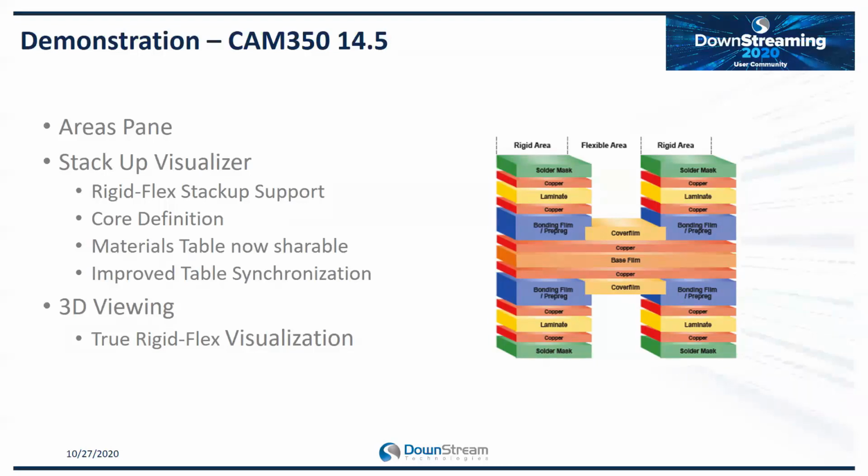2581 out of Cadence is pretty strong. They are passing the proper areas, but just recall, they are two different format specifications. So there'll be some things that you'll get from ODB, like areas, and some that you won't get from 2581 because the spec doesn't include them as of yet.